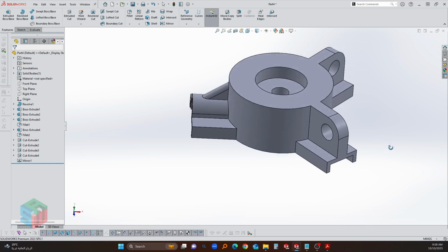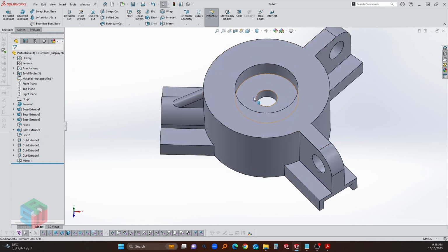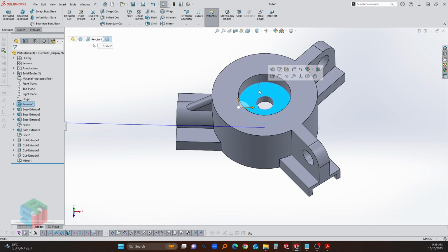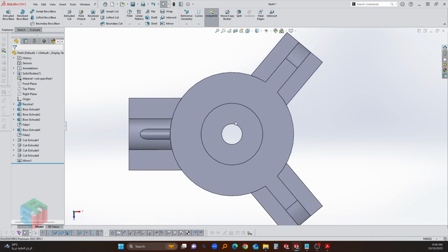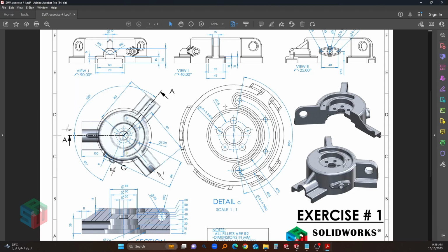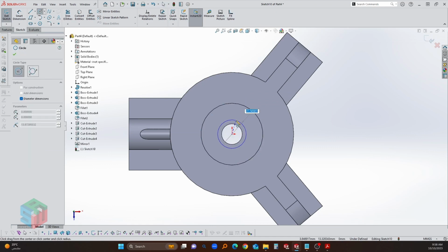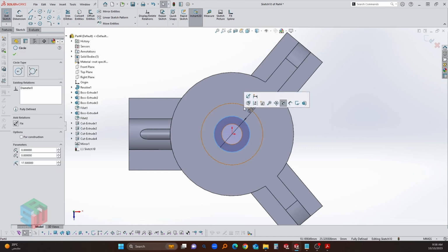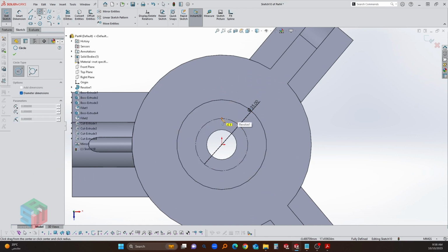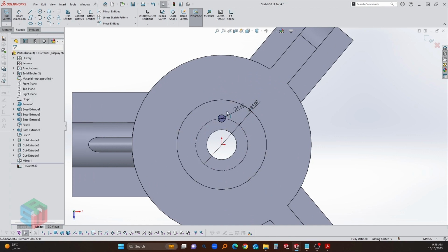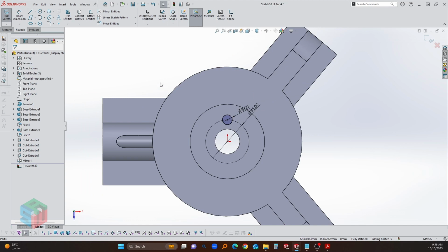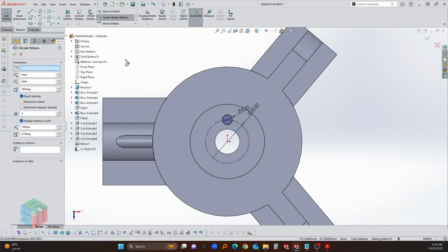Okay, now the final thing to do is to make the holes in the slot here. Let's do the holes. The holes are on a circle of 17.5 radius, so that's 35 diameter. I'm going to make a sketch on this plane. Use a 35. Make it a construction geometry and do a circle on top. This circle is 5, I guess. Yep. Oh no, it's 8. I'm sorry. It's 8.